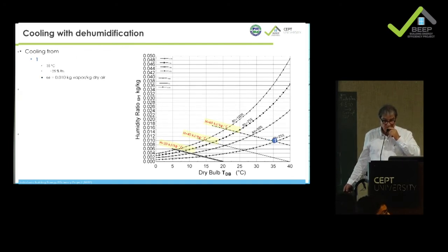Yeah. Then you are basically taking away heat. Heat, yeah, but no water. Not changing the water content, but you're changing the heat content. Yeah. Removing heat. So then, because the water is not changing, you have to be on the same humidity ratio line.